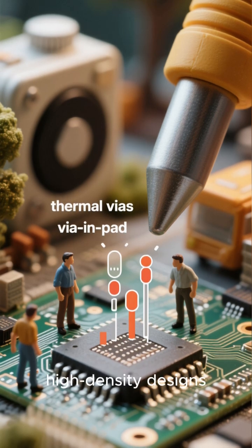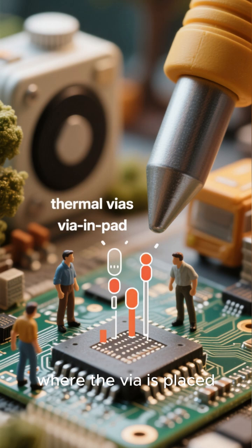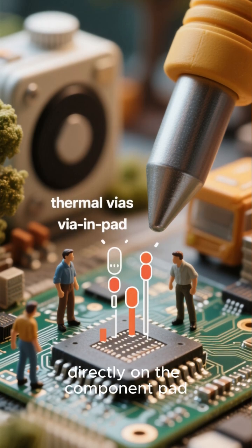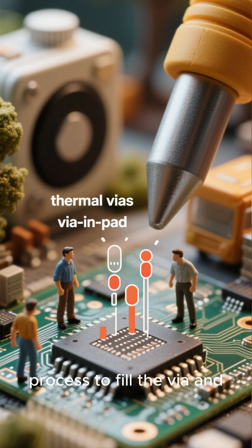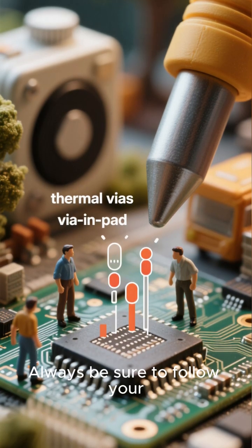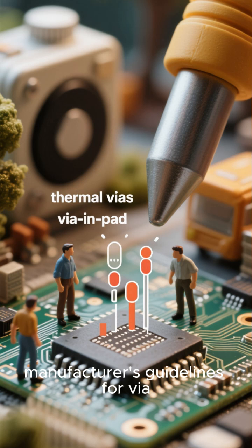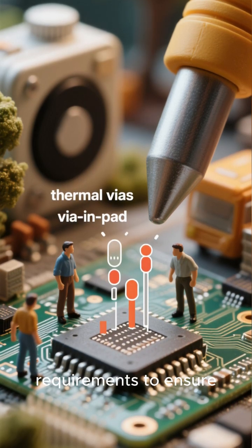In high-density designs, you might see via in pad, where the via is placed directly on the component pad. This saves space but requires a special manufacturing process to fill the via and prevent soldering problems. Always be sure to follow your manufacturer's guidelines for via sizes and annular ring requirements to ensure your board can actually be built.